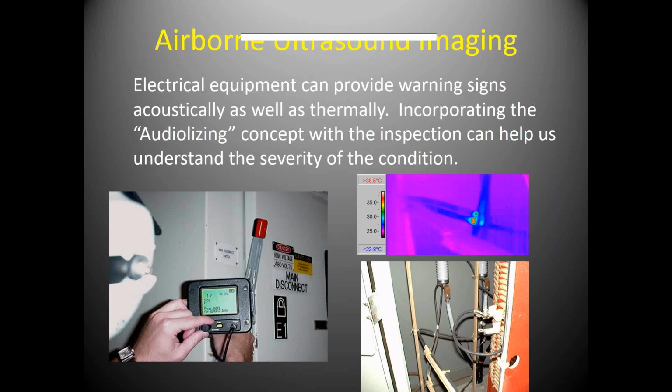Now here's a technician. Back in the 80s and 90s when we used this, I used to open up all the 480 boxes, and I would take the tool around the inside and listen for noises. Of course, when the new electrical safety rules came out in the early 2000s, you're not allowed to open the high voltage boxes anymore. So now we can take this tool with a little rubber tip nozzle and go around the seam of this electrical box, and you can see the technician here is hearing some noise inside. We don't know what it is, but when you hear noise in electrical, that means there's something inherently wrong in there. But if we open the box and look at the terminal strip inside, which they did with the camera here, you really don't see anything either.